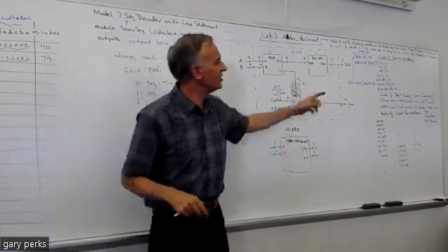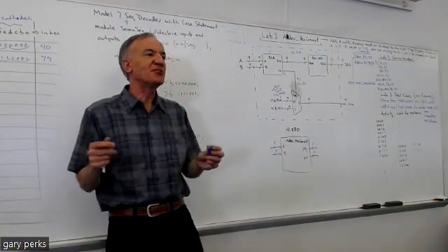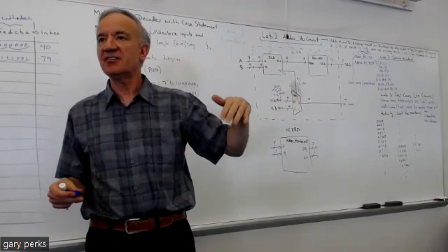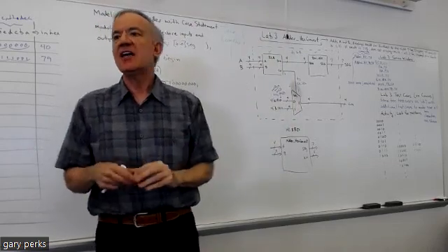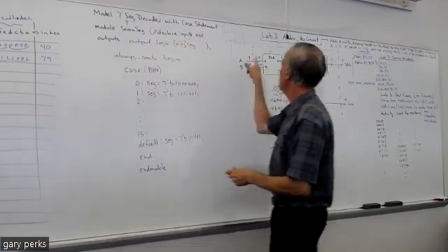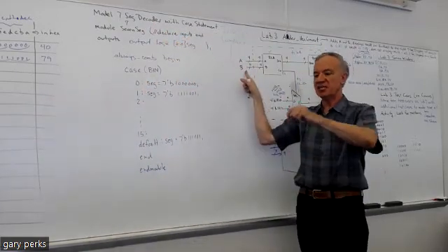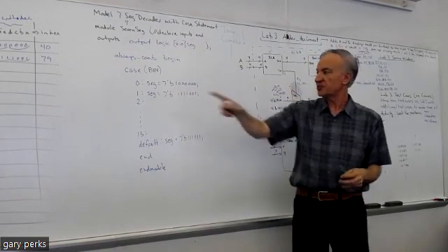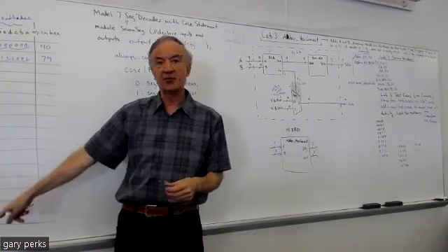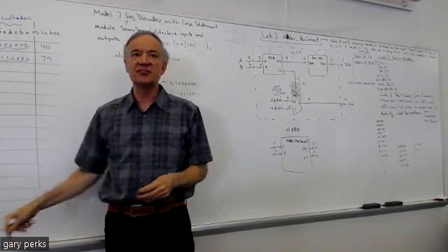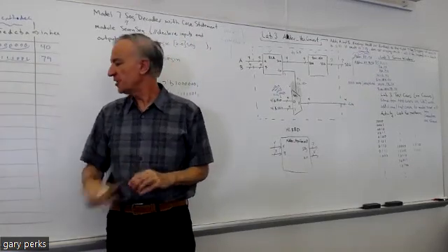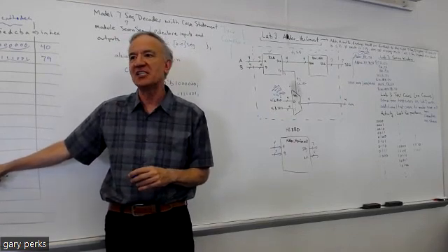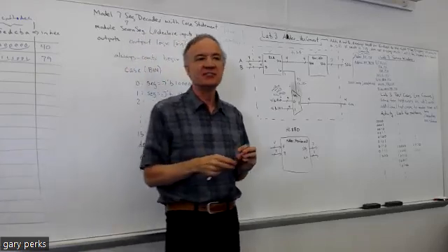Now you can see I didn't put a specific number because there's different ways to do it. I think the best way to do it, so you don't miss any, is to do the 10 for the RCA, just repeat what you did for lab 2, and then set one of your inputs to 0, like set A to 0, and take B and go 0, 1, 2, 3, 4, 5, 6, right up to 15, and show the grader that all these are being shown. Because we have to make sure you use the lowercase b and not an uppercase, because then you get 2 8s instead of an 8 and a b.